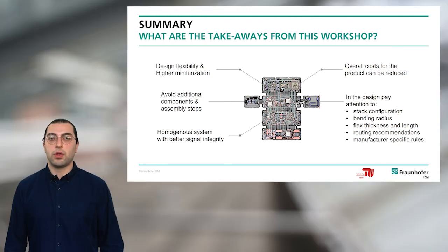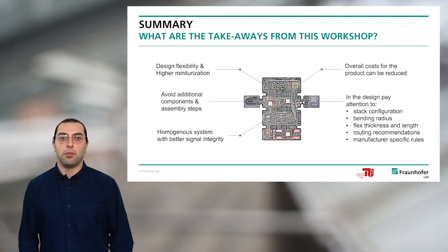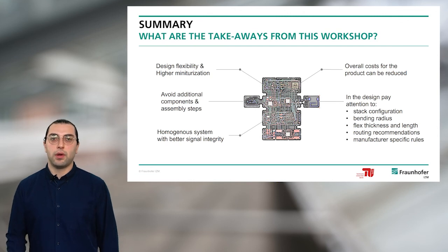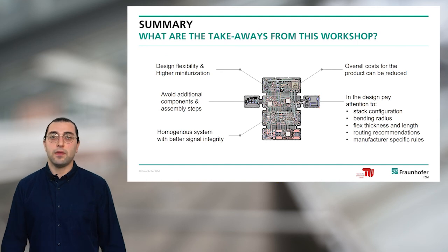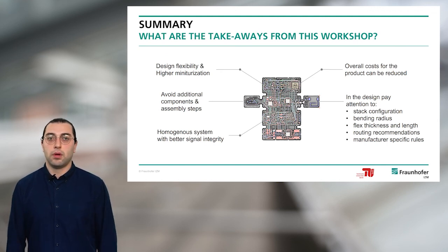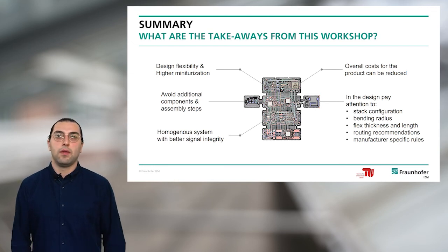We can also use rigid flex to have a homogeneous system that we can model and simulate better, with better signal integrity throughout the whole design. This points to the miniaturization, that we use only a smaller area, and the avoiding of additional components and steps. This can also help to reduce the overall cost for the product, but it always depends.